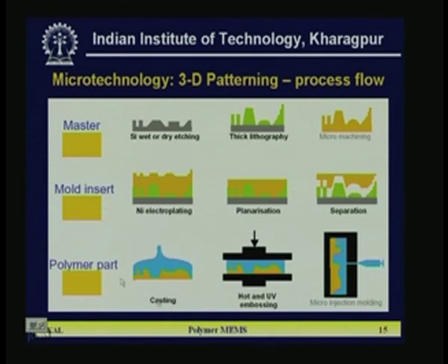Another technique is also followed, which is known as the micro injection molding. What is that? The whole structure you put it in an enclosure, then through a nozzle kind of thin needle you can inject the polymer into that, so that polymer will go inside and it will be deposited, fill the complete group with high pressure. So you can get the mold as structure, the flexible structure you wish, isn't it?